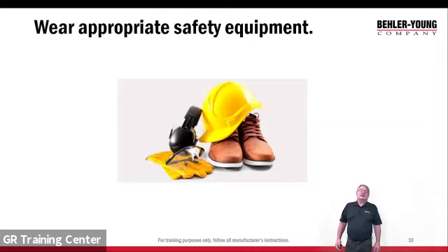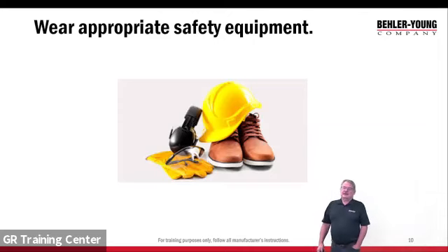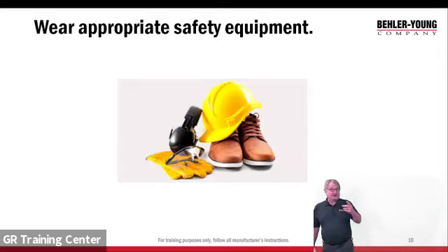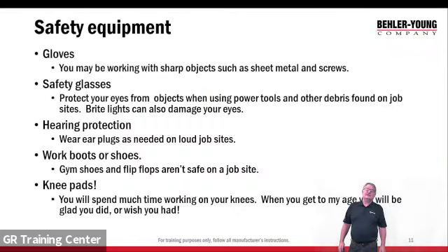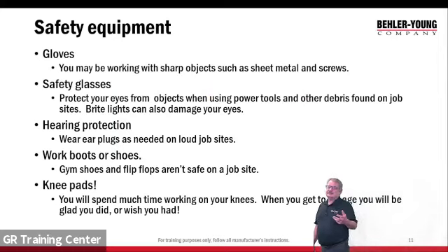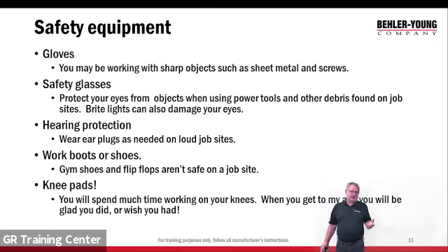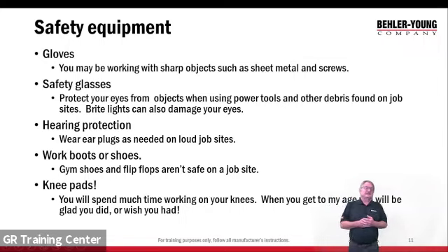Appropriate safety gear. We're going to be working with power tools, extreme heat, extreme cold, and sheet metal, which is very sharp, so gloves are a good thing. Eye protection, because we've got pieces flying when we're working on ductwork. Appropriate shoes: we shouldn't be wearing flip-flops on a job site. You want shoes that are safe for walking around. No tennis shoes, no flip-flops. Hearing protection, especially with some of the loud power tools. We want to wear hearing protection.